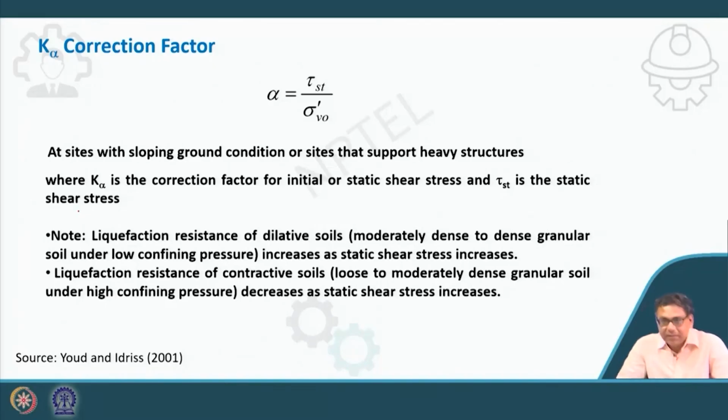But if it is loose to moderately dense granular soil under high confining pressure, which is the case we are more concerned about, then the liquefaction resistance decreases as the static shear stress increases. So it is very important to consider if the soil is loose, where your factor of safety will reduce, because the presence of static shear stress reduces the cyclic resistance as static shear stress increases.